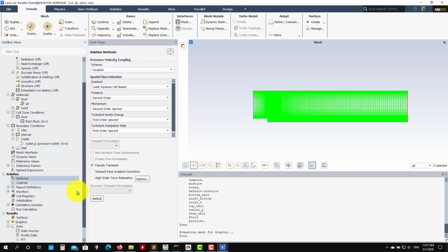We go into methods. So let's use the default method. Remember what I have told you, that for steady simulations this is the most robust method, so you can go and use it, but you can play around with different methods. Then you have, remember, always momentum. This you need to get second-order accurate solutions. Okay, so always momentum second order.